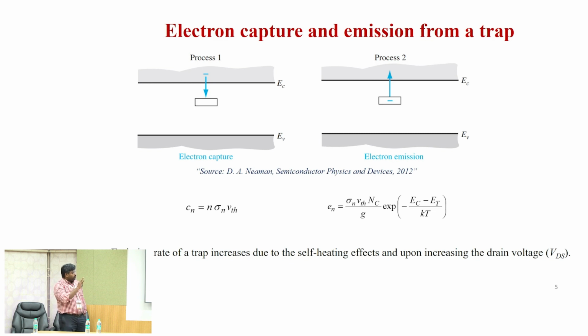Okay, so this is a general behavior, and the trap emission rate depends upon temperature, and it depends upon the electric field. If an electric field is there, your thermal emission rate will be accelerated by the electric field. Because of that, from the Arrhenius relation, you will get an underestimation of the thermal activation energy, and maybe that's why we are focused on calculating the zero field activation energy, or the actual trap activation energy, for a particular trap. So basically, it's a buffer trap only.